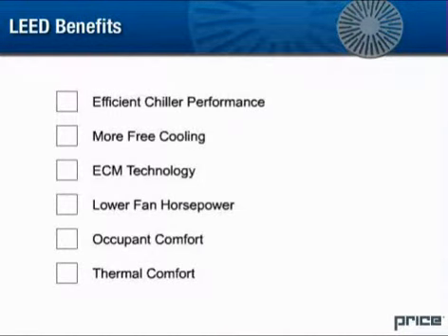To summarize, underfloor air distribution provides many benefits, such as a more efficient chiller performance, more free cooling, ECM technology, lower fan horsepower, occupant comfort, and thermal comfort, for reducing energy consumption and earning valuable LEED points.